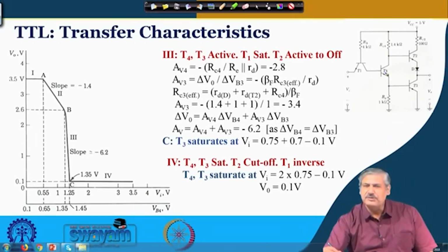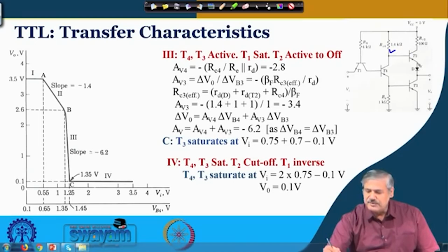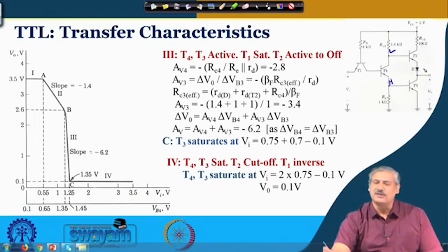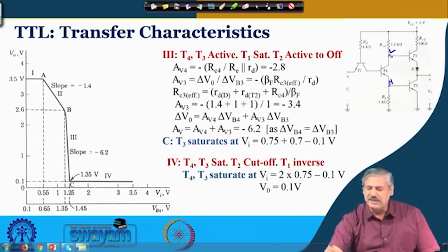And at that time, what is happening in that particular condition in region 4? So, this is in saturation, right. So, this time this is low in terms of making these two transistors on, and this is high in terms of making this transistor on. Okay. So, this transistor is on. So, 0.75 volt, 0.2 volt here, 0.95, which is not sufficient to drive both this transistor and the diode together on. So, this transistor will be off. Okay. So, in that perspective, when one is low, another is high, and when one is high, the other one is low. So, they remain out of phase, that is why it is called phase splitter.